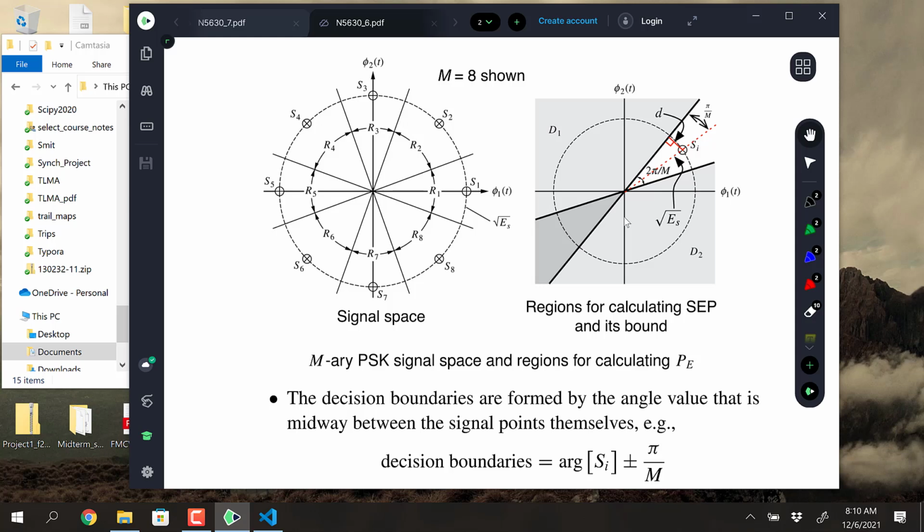But when you answered the one question on the exam, it was, what are the pros and the cons? You both had a con of QPSK as being 3 dB more, but that's not true. But it is more complicated. It's more sensitive to the phase imbalances. So you can think about it, but that's what it is. And it's one of the fundamental things, which is why Dr. Zemer has that question in there. We're interested in the serial bit error probability, and that's what makes QPSK pretty nice, because you can demodulate it in phase to get, say, the even bits, and then the quadrature gets you the odd bits, and then you're immediately demultiplexed into two.